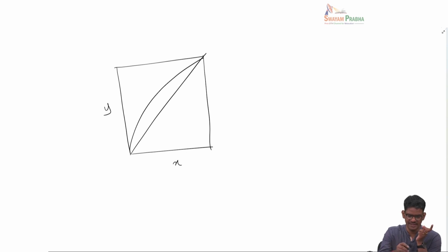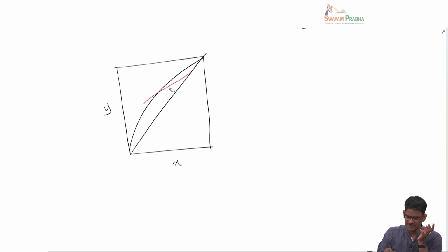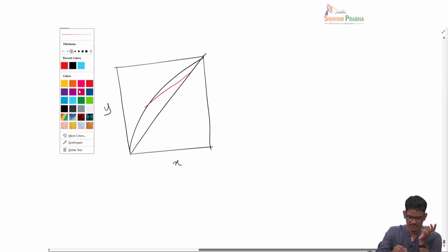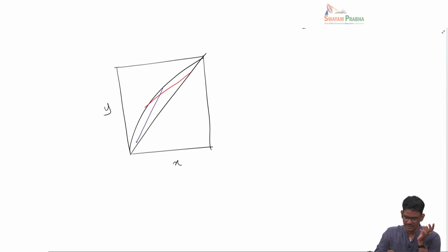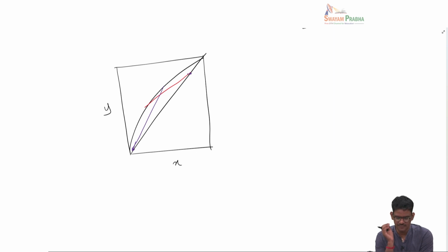We will draw two operating lines, since the distillation column involves different flow rates. The red line is drawn for the absorption section at the top of the column, and the purple line is for the stripping section at the bottom of the column.